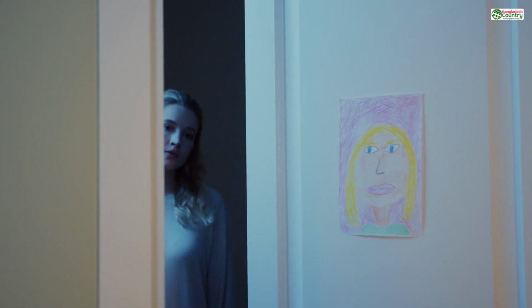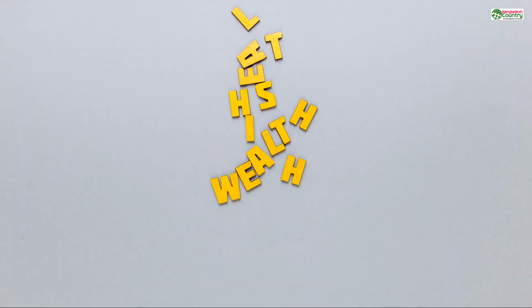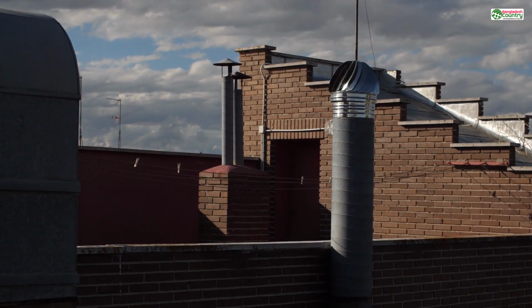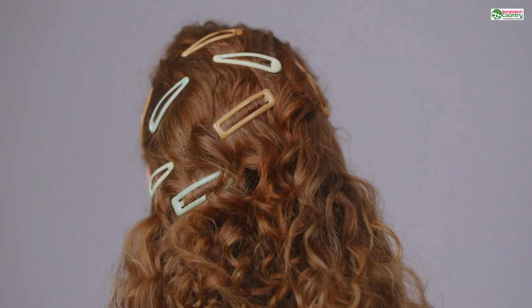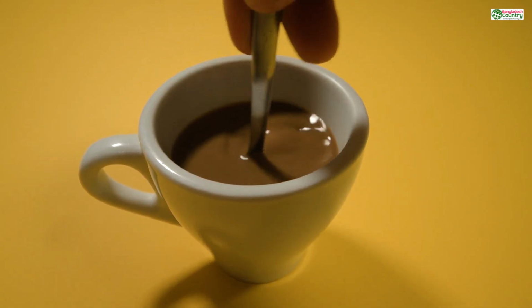He uploaded it to an SLS service to be printed in tough nylon. The quote was high, but he figured it was worth it for his masterpiece. When the part arrived, it was a disaster. The sleek vents, which looked so cool on screen, were so thin they had warped from the heat of the laser. The snap-fit clips he designed to hold the case together were as thin as a credit card and broke the instant he tried to close it. The entire thing was a flimsy, useless piece of plastic.